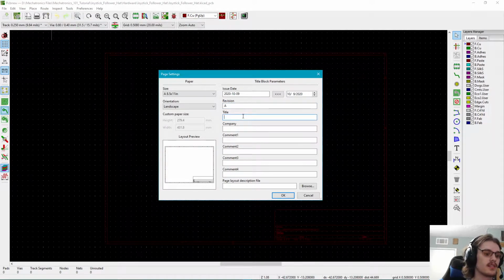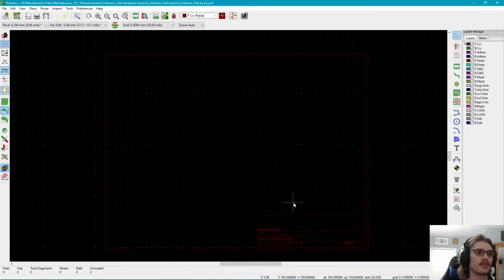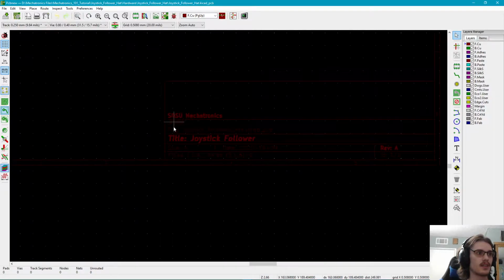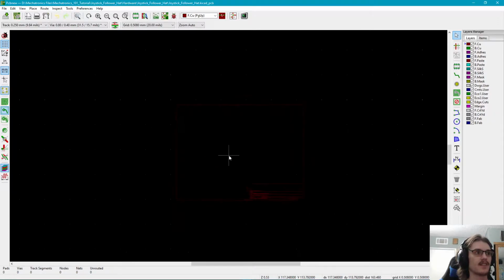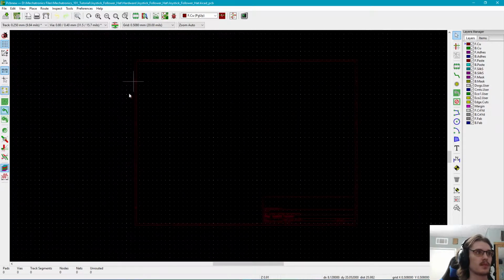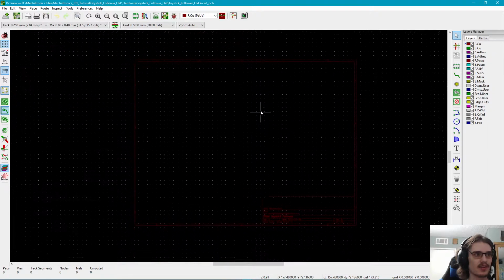The title, this is a joystick follower. The company, I'm just going to put SDSU Mechatronics, but this can be whatever you want. And if you would like, you could put some comments, but I'm not really going to fill that out. So we hit OK. Now if we look in this corner, we have our title, our company, the file it has, what rev it is, and other details that are automatically set. Now, also, the paper size is smaller. So that's what that did.